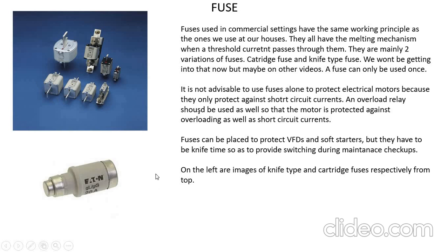And I also want to state that it is not advisable to protect electrical motors with fuses only, because fuses do not provide protection against overcurrents. They only provide protection against short circuit currents. So if you're going to use a fuse to protect an electrical motor, you have to also provide an overcurrent relay or something like that that can provide protection for overcurrents, because otherwise you can cause problems to your hardware or your electrical motors or loads.